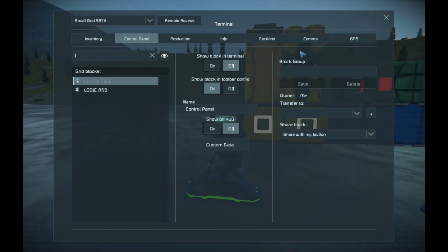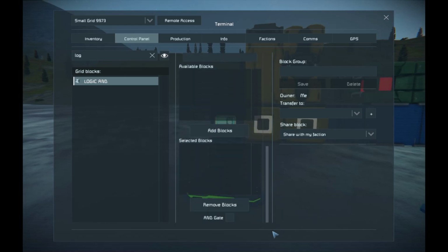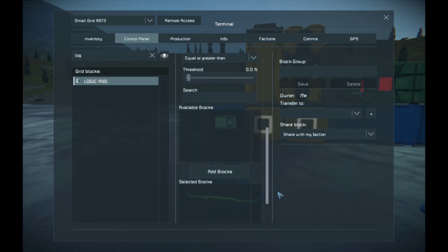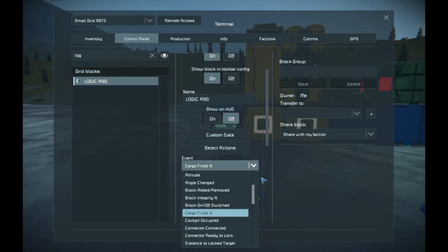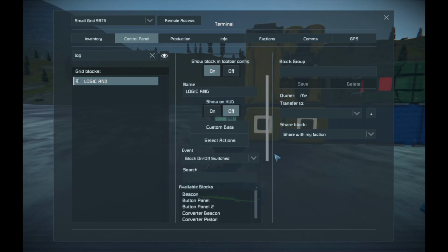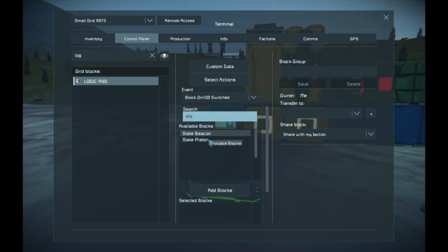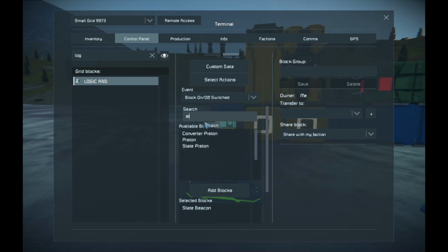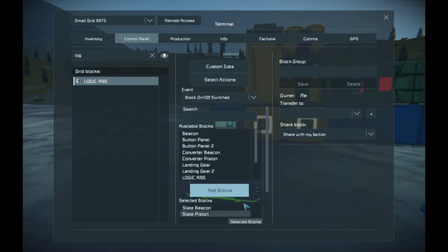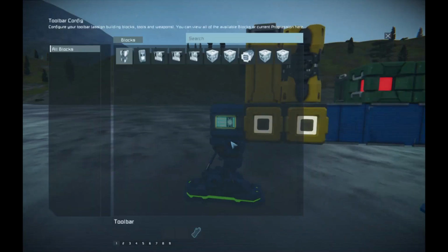Now we set up the logic event controller, in this case, the AND gate. We switch the AND gate checkbox on, then we select the block on-off event, and add the memory timers which are named state. Once that is done we set up the actions for the output timers. The AND gate returns true when all inputs are true, so in the first action slot we turn the output timer on, and in the second slot we turn the timer off. We do the reverse for the NAND, aka NOT, in the second toolbar. The upper output timer is for the AND gate, while the lower is for the NAND gate.